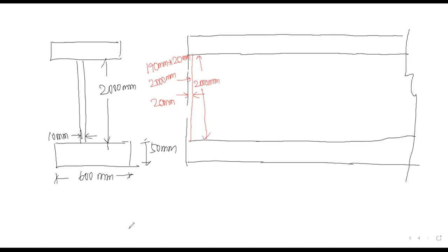Now we have to design the intermediate stiffeners. We have to assign the thickness and check whether it is safe to transfer these forces, the bearing or whatever load carrying.